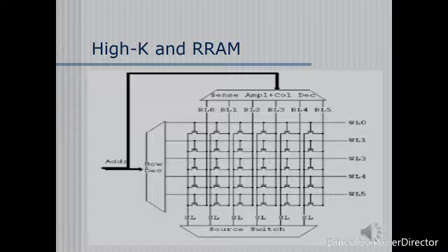With outside voltages through the top control gate, it creates a voltage drop over the dielectric between the floating gate and the silicon substrate, creating carrier transport through the tunnel dielectric, or the minimal amount of bias to read the charge stored in the floating gate. When the size becomes smaller, less than 40 nanometers, the floating gate architecture must be modified because the physical space between the cells becomes too small and does not let the control gate cover the floating gate.